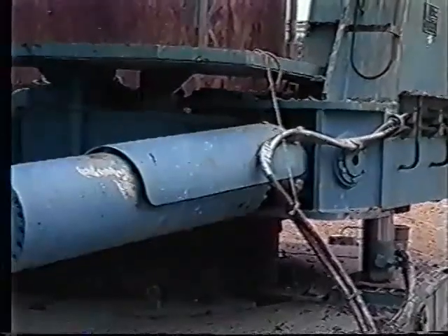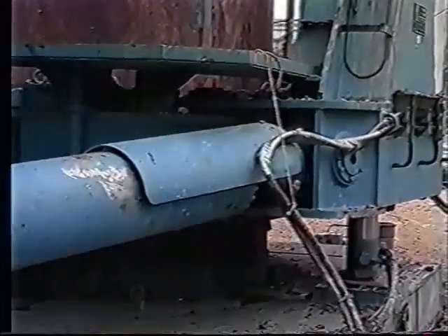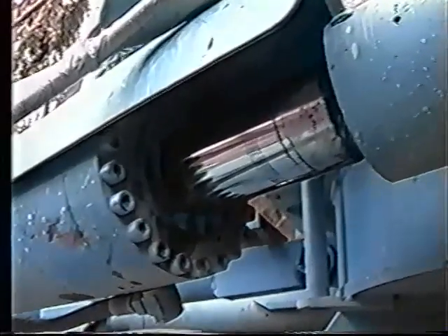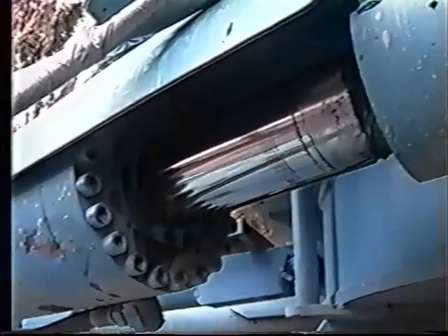The casing is pulled and twisted into the ground by hydraulic jacks with torques of up to 6 million foot-pounds. Drill casing is available in lengths of up to 8 meters. During the drilling, sections of casing are joined by tightly fitted collars with inset conical casing screws. The wall thickness of heavy-duty drill casing ranges between 40 and 60 millimeters.